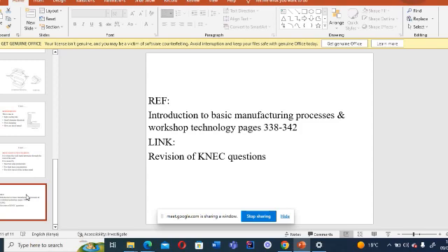So before I close, let us recap on what we have learned today. What have you learned today? Yes, Gavin. Today we have learned about the welding defects. For example, porosity, which occurs when gas bubbles become trapped in the welding metal, leading to small voids or cavities. Thank you.